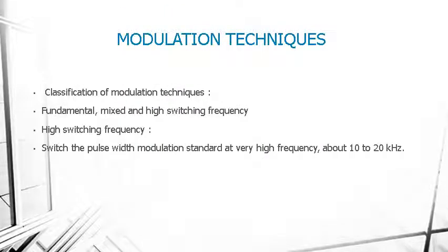Modulation technique. By the modulation technique, we mean how to generate the necessary train of pulses to control the inverter's switches according to the required output voltage, the reference voltage. The modulation algorithm used to drive the multi-level inverter must be aimed to give the voltage level required for each leg. The transition in the proper switches configuration is done by another algorithm, which can be hardware or software implemented.